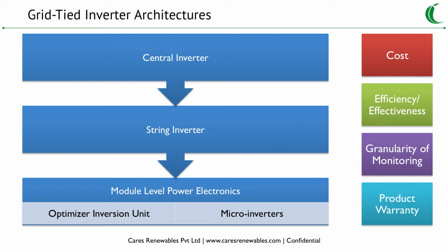Now, if you look at architecture, one inverter architecture which I didn't speak of was the central inverter. Central inverters are typically very big in size, and not much used in plants below 100 kilowatt. One inverter will be 100 or 500 kilowatt, or a megawatt or 2 megawatt, and these inverters are similar to string in design, but you will have a large number of strings which form what you call an array. When you have a large number of strings connected in parallel, it's called an array.